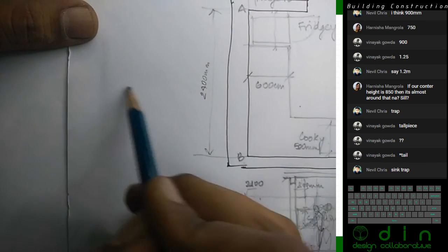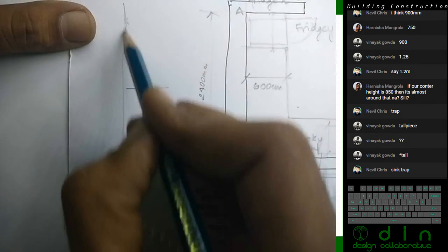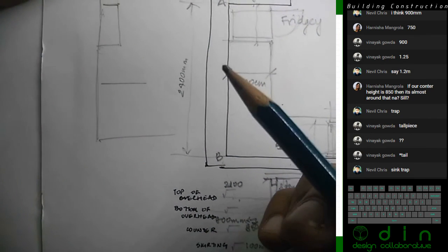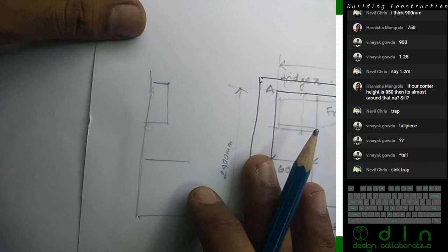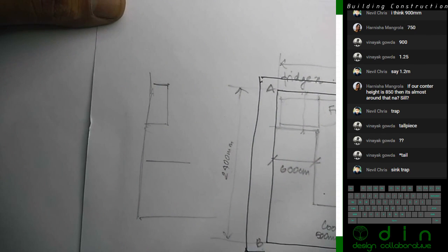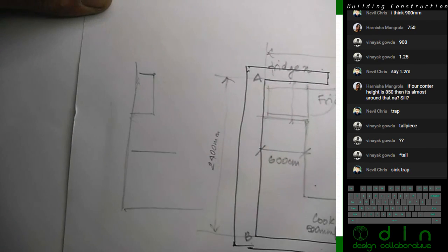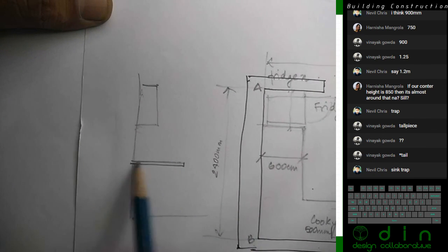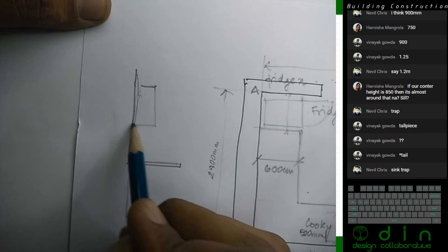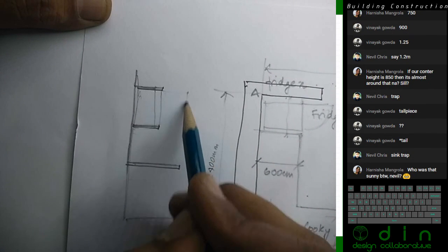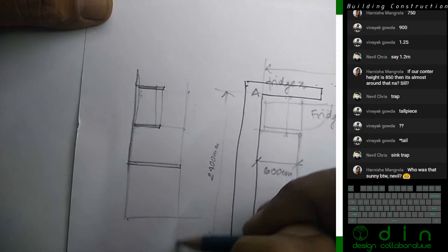Alright, I can draw that in section. That is the one thing that I wanted to explain. One important thing is the below counter things. The door will be about 450 wide, mostly because of the weight that the hinges can take. For our overhead cabinets, the height that we use is 300 mm, mostly so that when you open this door, it's still within that. You don't have to move back.